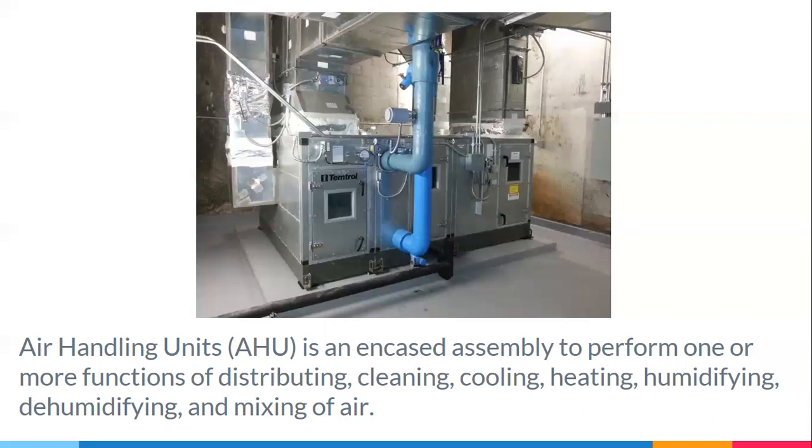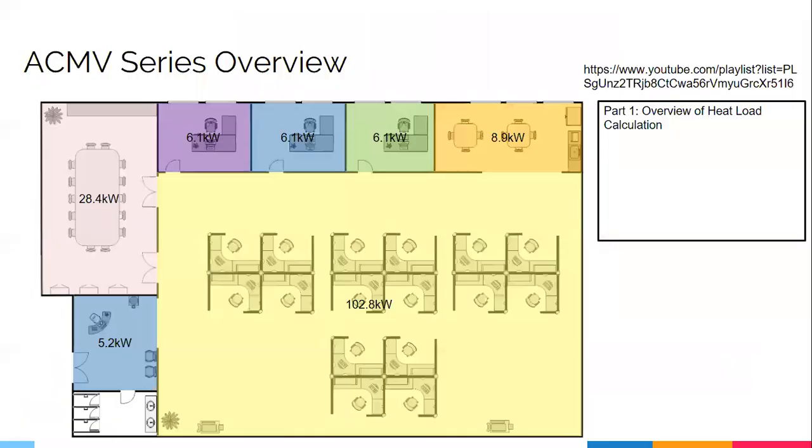So when you give your requirements to the manufacturer, it is understood that the pressure you are giving them is an external static pressure loss. The internal pressure loss will be calculated by your manufacturer and added accordingly to the size of the fan. Okay, so clear? What we're going to calculate is the external static pressure.